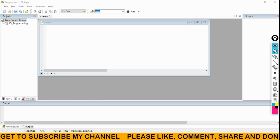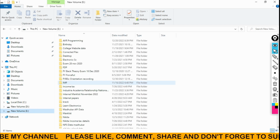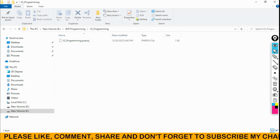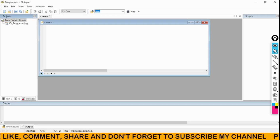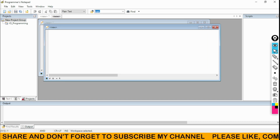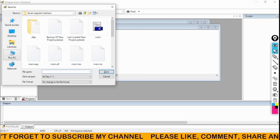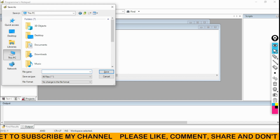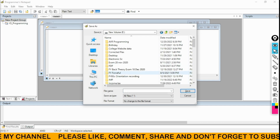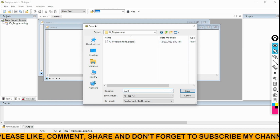If we go into the folder, we'll see the project is created, the IO program project file. The next part is we have to take a new file and save it by using Control S. You have to save it to the location where the project has been created. Go into IO programming, and we have to give the name main.c.